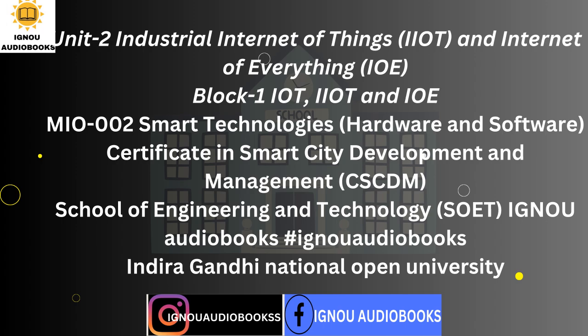historian cloud connection. The backhaul network connects the plant to the cloud data center, enabling connected services. The media can be the plant's broadband internet connection or a separate mobile, cellular network connection using a mobile, cellular router. IP is used as the transport protocol supporting many application protocols. For a mobile network, cellular network, or satellite network connection where the data charges are high and the bandwidth limited, it may be necessary to use slow polling rates and data caching and report by exception techniques to reduce the data volumes to keep the data charges low.